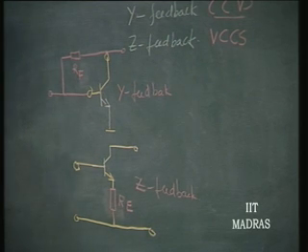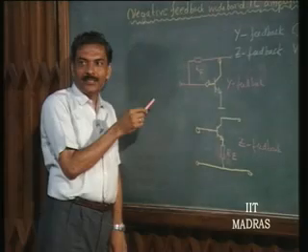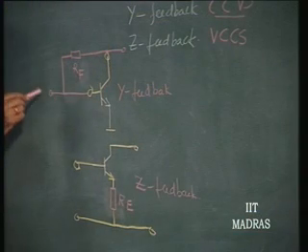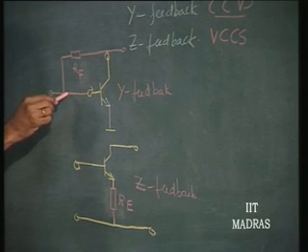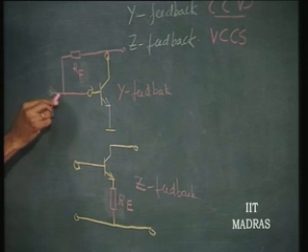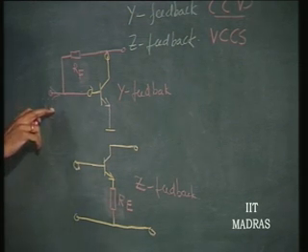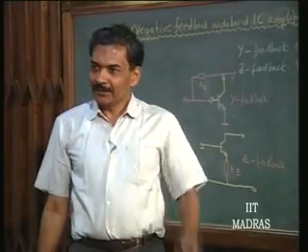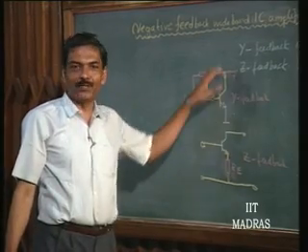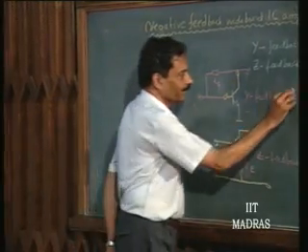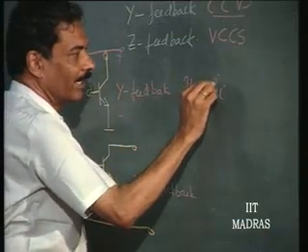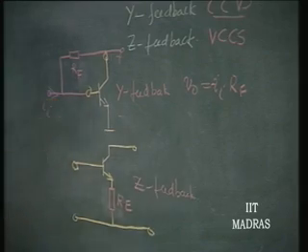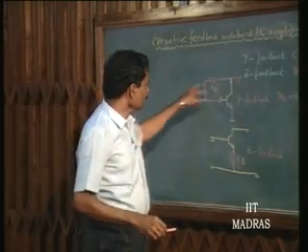So, what will be the transfer parameter that is going to be desensitized in this particular case? Forward transfer what? It is a relationship between current and voltage. So, forward transfer resistance, right, because II is the input current, and this II is going to flow through RF totally and result in a voltage which is II times RF, with the ground terminal being positive and the output terminal being negative. That means, there is an inversion. So, V naught is going to be minus II times RF. Is this clear? This II will be going through this, totally. Very small current is going to flow through the transistor amplifier. Most of it will flow through RF. Why?